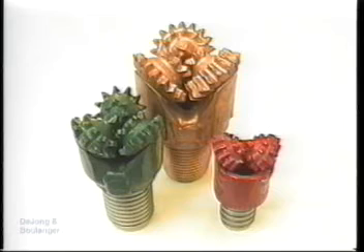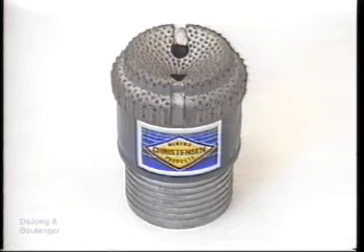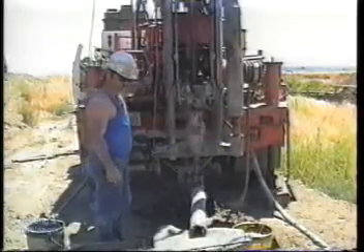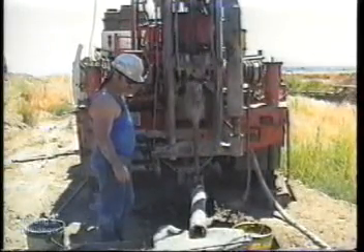The cone bit has teeth on the surfaces of cones, which rotate as the bit is turned. The spacing and size of the teeth on the cone depend on the type of material to be drilled. Plug bits come in 3 basic types: concave, pilot, and tapered. The concave plug bit, pictured here, is designed for drilling through relatively soft rock. An important difference in bits is whether they are face discharge or side discharge.